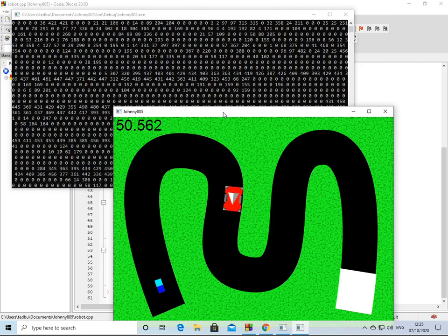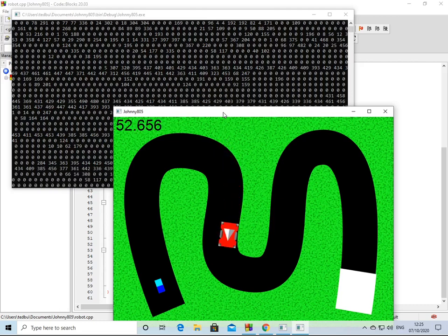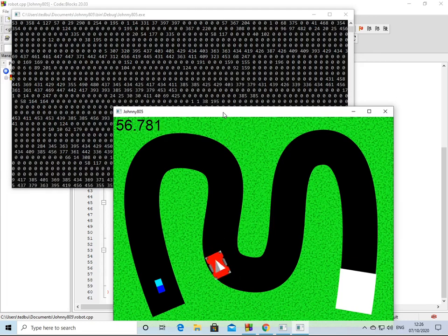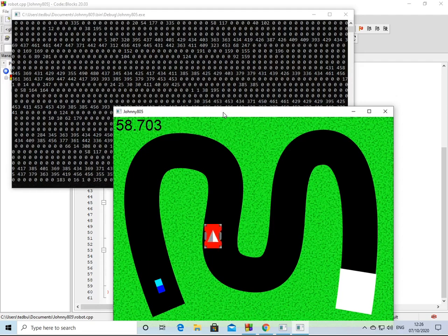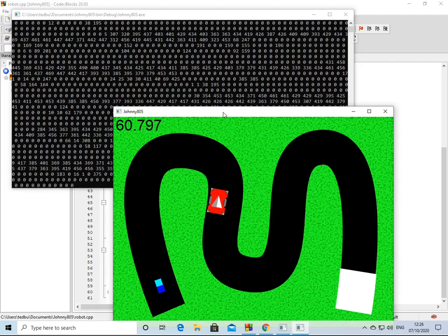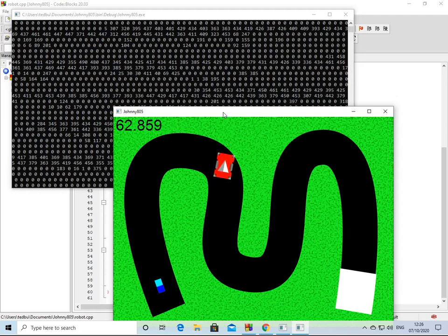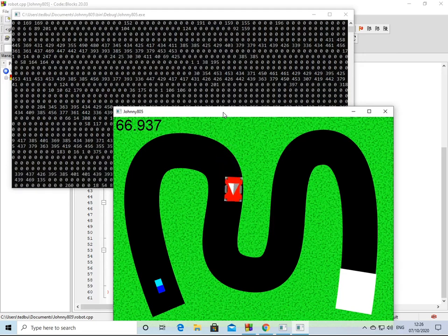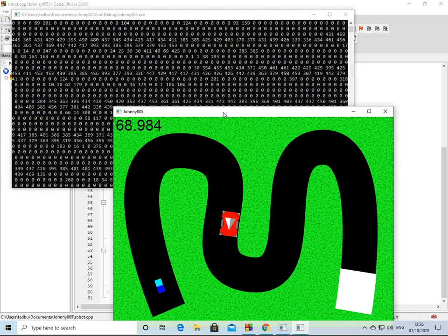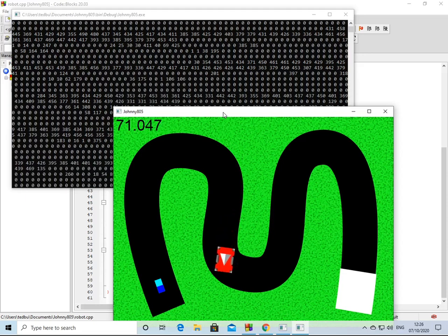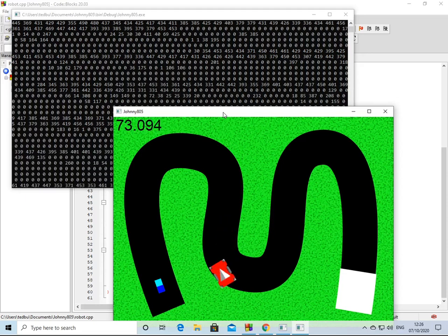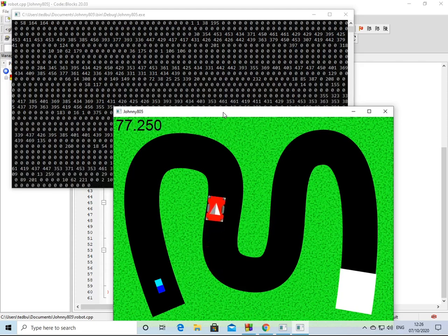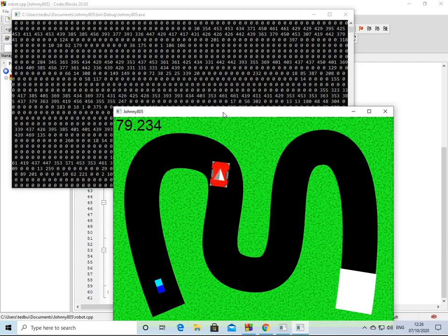Now it's not a uniform number all the time for green, because the green color of the ground there is kind of mottled, so it's darker in some patches and lighter in others. But you can see roughly you're getting values in the 300s and 400s. Now when you get to the parking space at the end, if you can get the robot to go that far, you'll see that the numbers will read a lot higher. They should be up well over 1,000, I would say. The maximum value is 1,023, and it could be quite close to that.